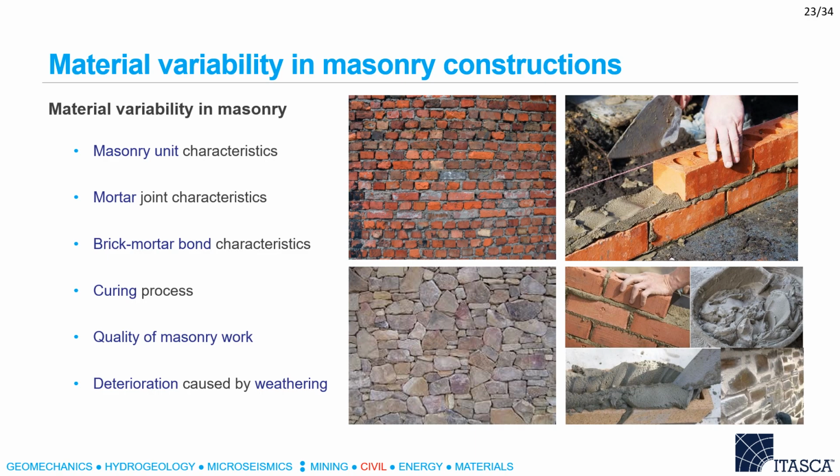Masonry material properties are characterized by inherent variability, and this is due to composition and quality of materials, workmanship, curing effects, weathering, etc. However, today engineers are assigning the same material properties throughout the structure to be analyzed. In this research, we propose the development of a DEM model for masonry able to consider the stochastic variability of masonry material properties and investigate how these affect the load carrying capacity of masonry structures.